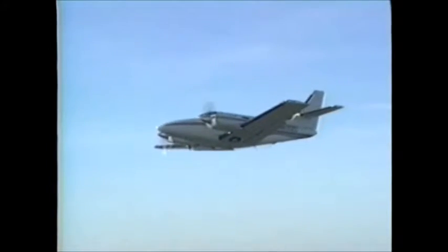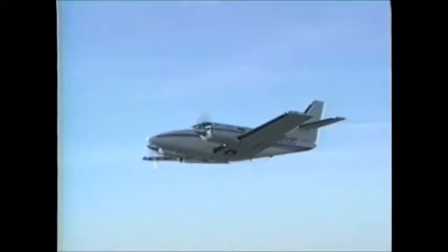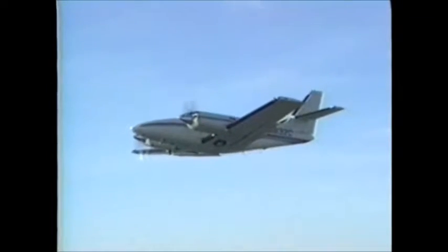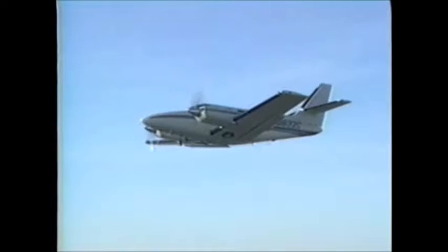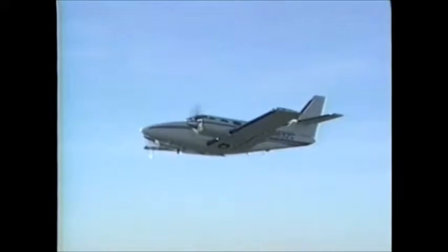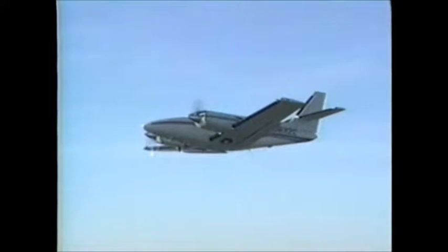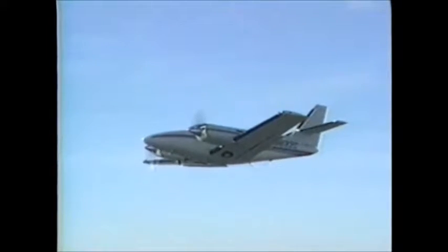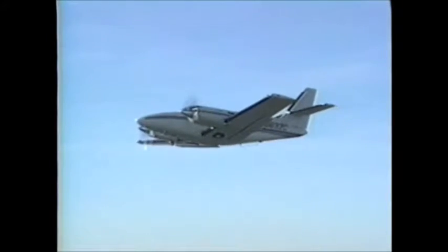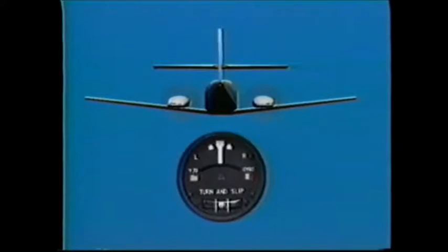It's important to realize that at any given time, an airplane's actual VMC may vary due to changes in weight and balance, density altitude, power settings, and aircraft configuration. It's a common misconception that when an engine fails, a twin is flown wings level with the ball centered. Let's look at why this is not a good practice.